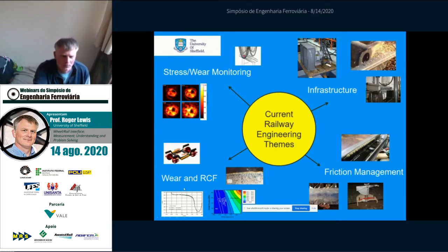And then finally, where I started in my work in railways, in wear testing and modelling of wear in railway wheels. So the focus of my work was largely around understanding the material removal mechanisms, but also to develop wear models that could be integrated into tools based around multi-body dynamic simulations to predict profile evolution.